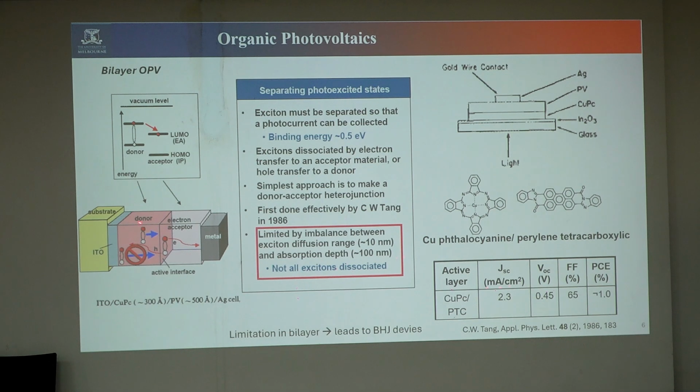Okay. So what we need to consider is that when the exciton is generated here, it must diffuse to the junction, and only then will it get dissociated. So the exciton should have some diffusion length. This is an intrinsic property that depends on the material we are using, like the dielectric constant, and then the diffusivity will be very high. Right now the diffusion length of the exciton is very low, less than 15 to 20 nanometers. That's why the domain size needs to be less than 20 to 25 nanometers. Then only can the exciton diffuse to the donor-acceptor junction.